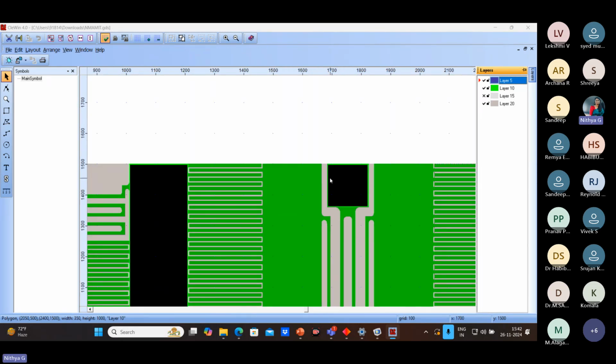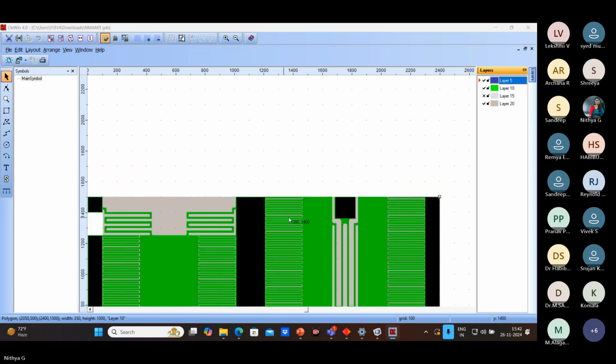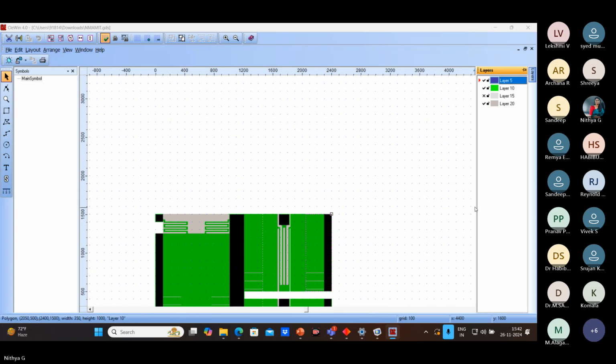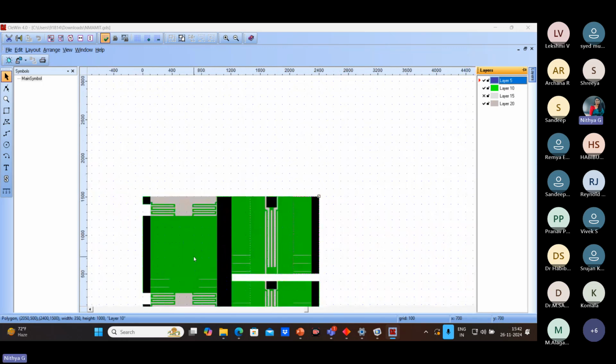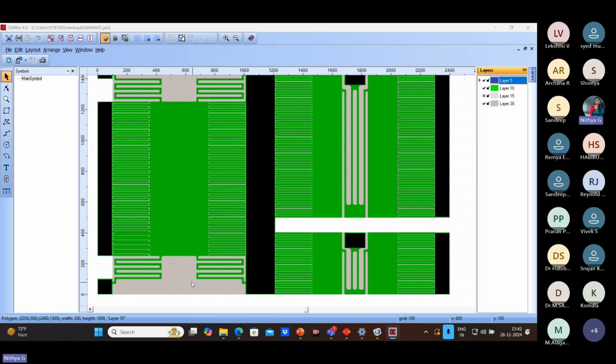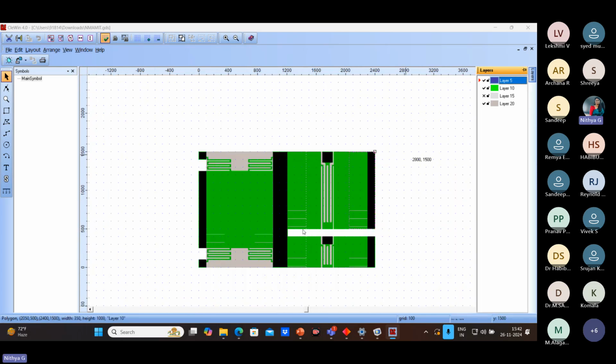One thing, I need to take a layer. So let us do the design. Just remember, we need to take a few layers. We need to keep some minimum distance between the layers so that they do not overlap and cause the removal of the device layer during the fabrication, during the etching process. And one more thing to say is, okay, whenever I start the design, I'll tell that point. So I hope this is now known to you, right?